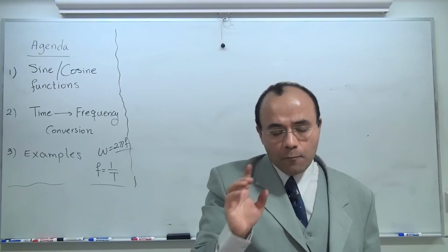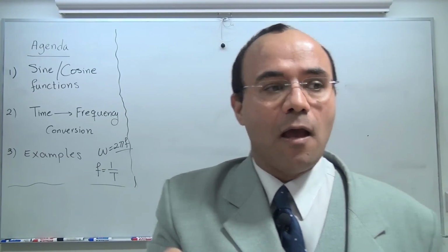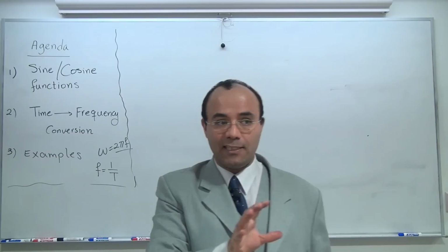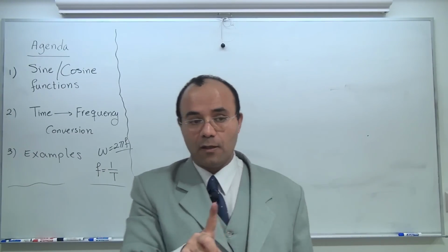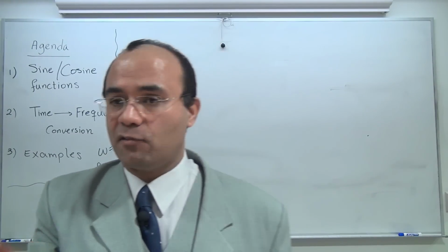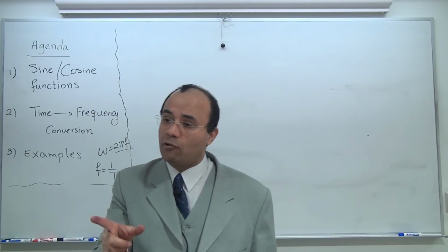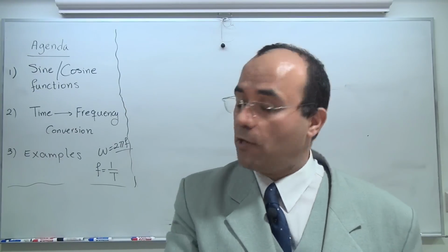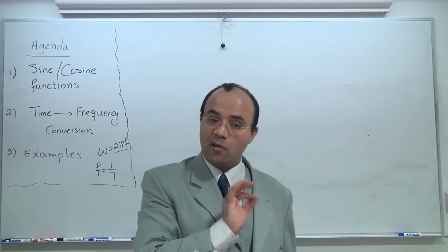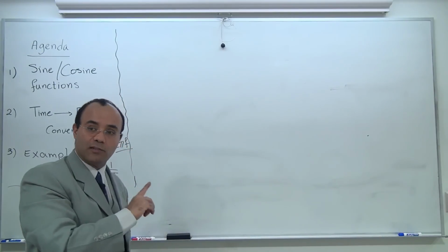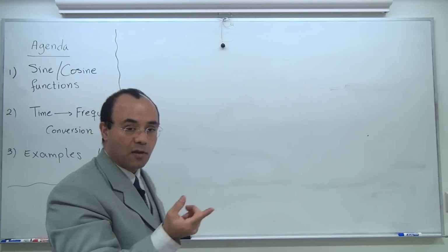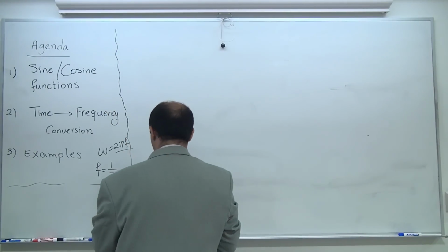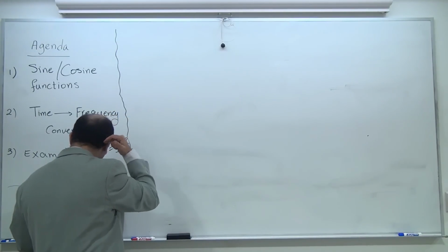Remember, when I take this to the frequency domain, I'm going to ignore the transient response. All I can guarantee you is the steady state response. And if you have an interest in the transient response, you need to establish your differential equation no matter what the degree is. If it happens to be a 10th degree differential equation, so be it. Transient response is not captured by the method I'm trying to achieve today. There are Laplace transforms and everything else that would capture it, but I don't want to go that far. Nobody in this class has shown interest in Laplace transform.